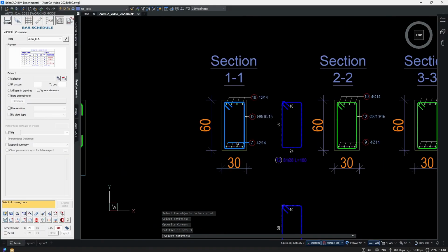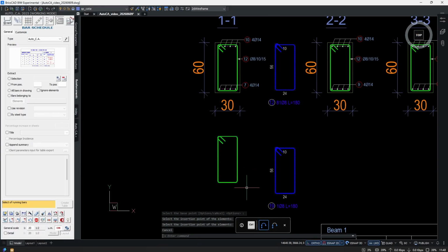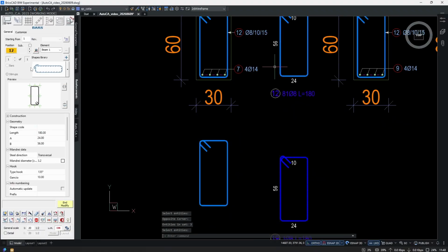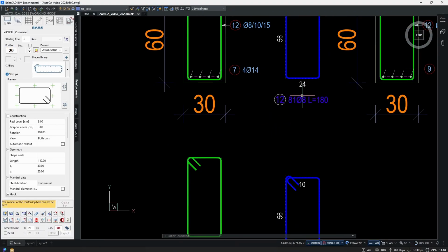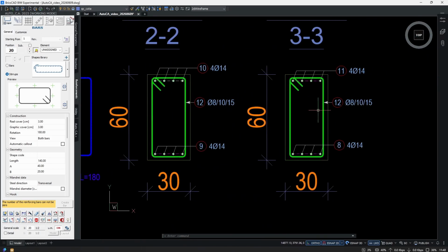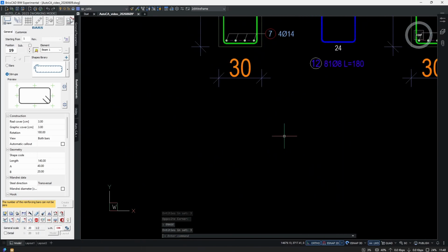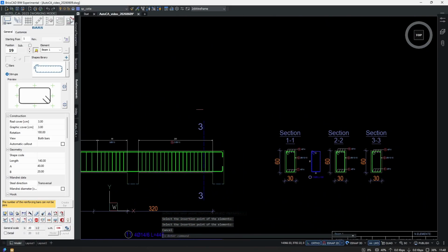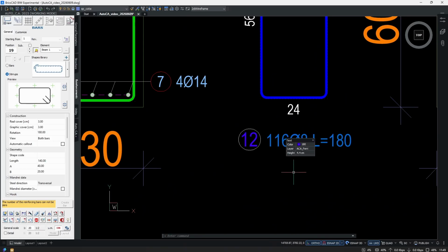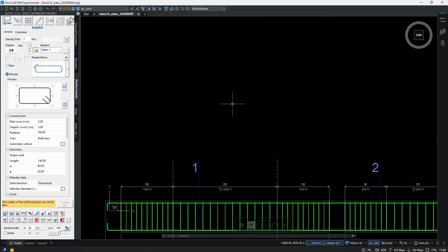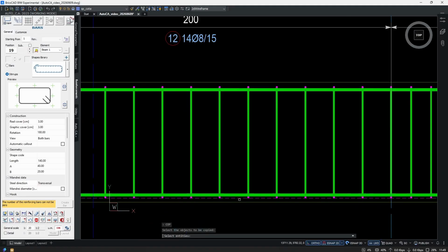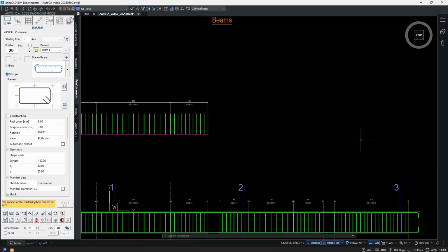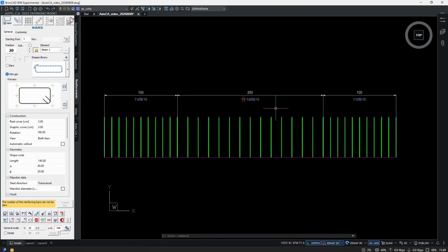piece. If you copy only the internal bars, you will get a new inside bar, which is linked to the original outside bar, you can see. So that's how we created the other cross sections. If you copy only the bar series distributions, the quantity automatically updates at the outside bar. And if you copy both simultaneously, you will get a new outside bar with the same quantity as the original one, thanks to the distribution.